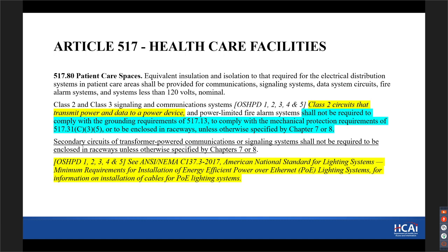Thank you. For OSHPD 1 facilities, the lighting switch low voltage that has multiple switch legs for normal and emergency power has to be separated per power source? Correct. Yeah, Article 700 is pretty clear that you can't combine them. The only place where you can combine normal and emergency would be in a transfer switch, or in a light fixture. So yes, that would need to be separate.